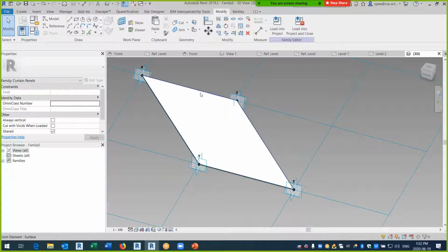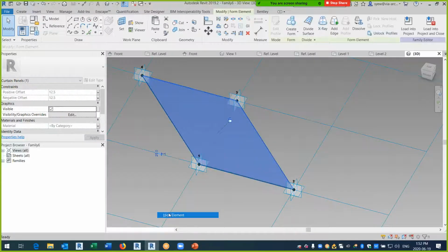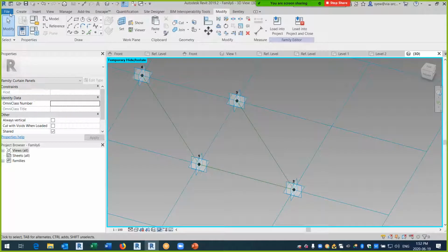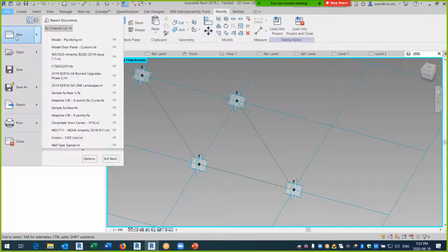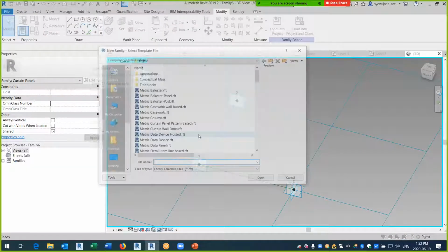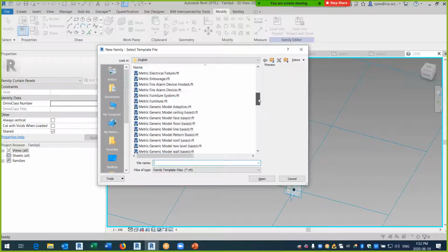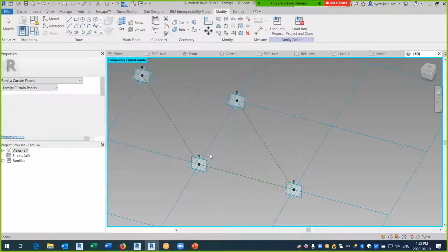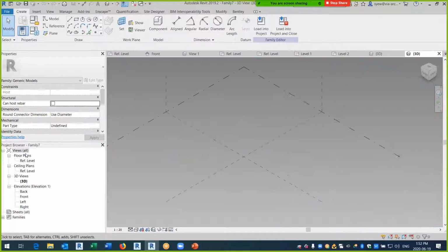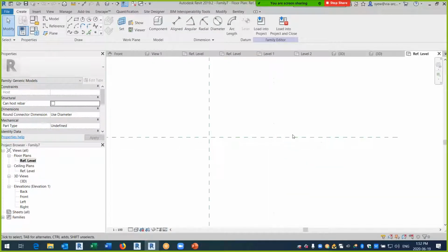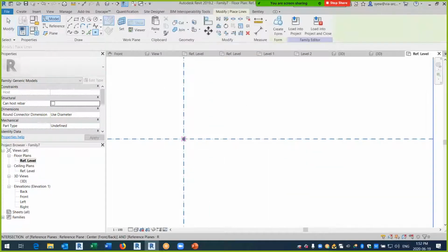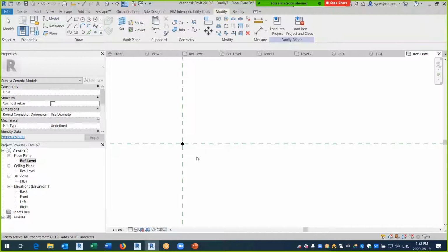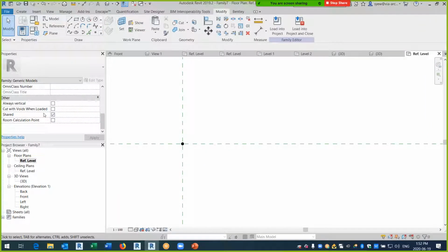Now, if you want to build a frame around that, what I like to do is create a profile. So here, I'm just going to go to Family. Just use the generic adaptive. So what you're going to do here is add in a point. Now, one thing to keep in mind with adaptive components is that it's always set to share. Sometimes you don't want that.